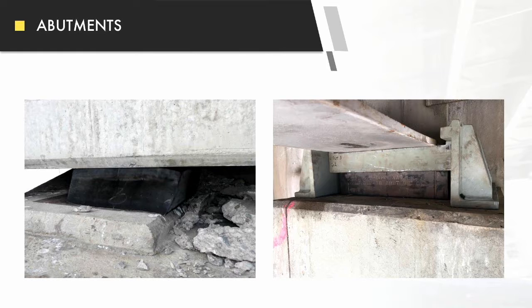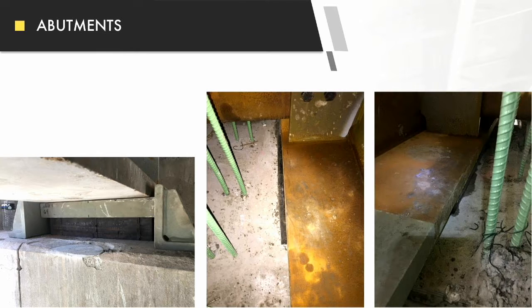This one over here, it's so bad. It's not centered on the pedestal. It's not bearing top to bottom. It's bulging on the side. It's kicked offset. That structure is doomed from the very beginning. So even though it doesn't seem like an important step, it's a very critical step to make sure they're placed right for the longevity of the structure and the way it's supposed to be done.